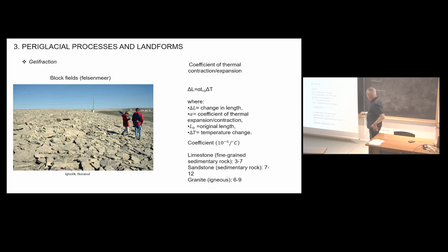And you see here the coefficient is pretty low. Sandstone will react well, and granite will be in between. Granite is an igneous rock. It's not a sedimentary rock, so it's not porous like sedimentary rocks. And igneous rocks will have different minerals. So then we talk about the thermal expansion and contraction of the minerals inside. They have different thermal conductivity, these minerals.